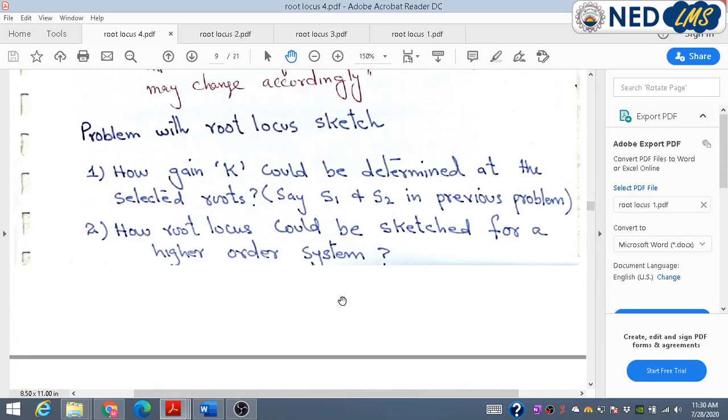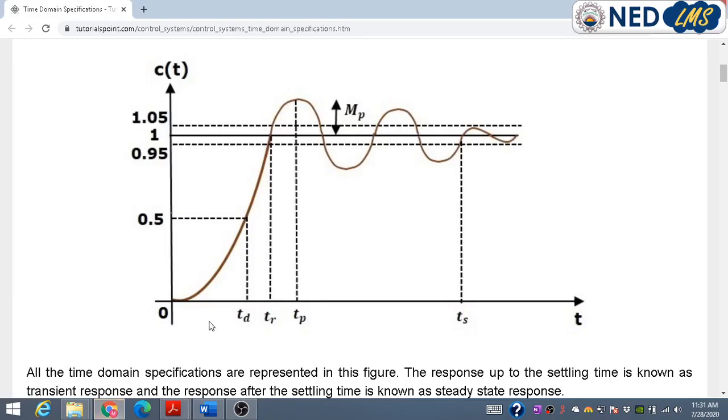And after the determination of this k in real practice, if we set the particular value of k that we have determined for these two search points, it will automatically set the system response which we want the system to produce in terms of its overshoot, which should not exceed the required limit, which we have said earlier is about 20%, and the other time response characteristics like TR, TP, and TS, the settling time. If we have found the controller gain and we apply it in the real system, in real practice, that would automatically set our time response characteristics.